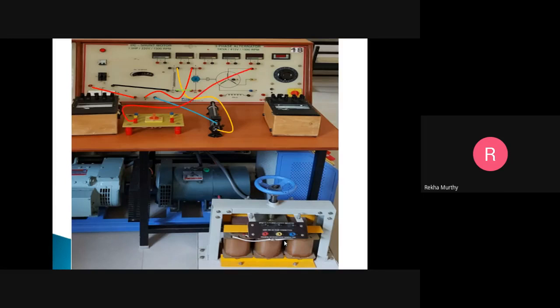Coming to the alternator, one end of the TPST should be connected to U, V and W. The output of the TPST from U should be connected to the wattmeter terminal M, and MC should be shorted, and L should be connected to one end of the inductive load. The other end of the same V connection should be shorted together, and the interconnected point should be connected to the ammeter, and the other end of the ammeter should be connected back to the V position. The output of the other side of the TPST should be connected to M, MC should be shorted, and L is connected back to the load.